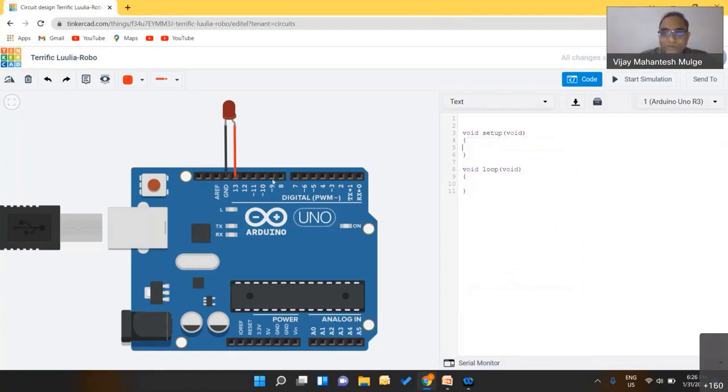Now, is there any pin that I'm considering as an input or output pin? Look into these digital pins D0 to 13. Which pin am I using? I'm using pin number 13 here, right? I need to indicate whether pin number 13, that I'm connecting my LED to, is an input pin or an output pin. I need to make this decision here.